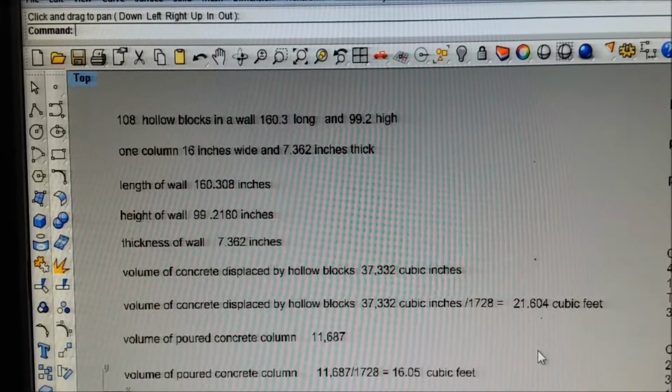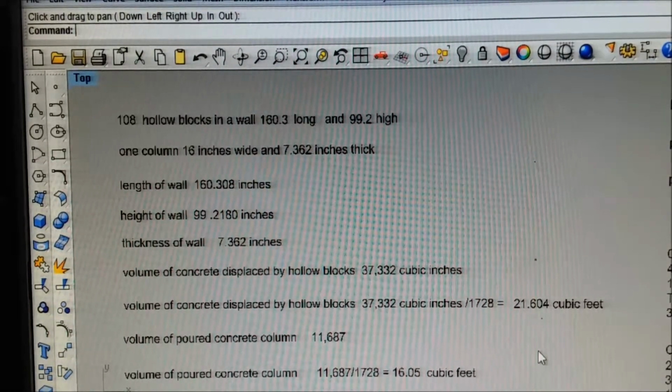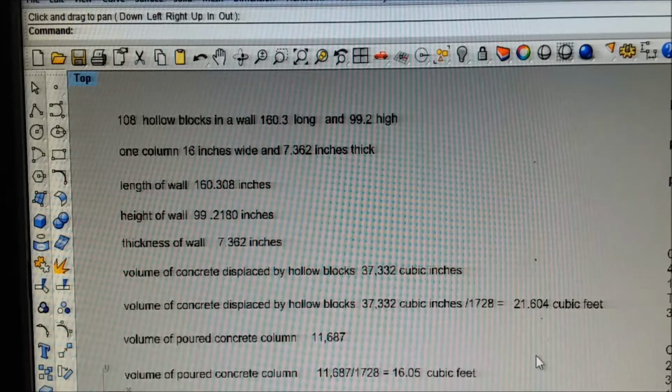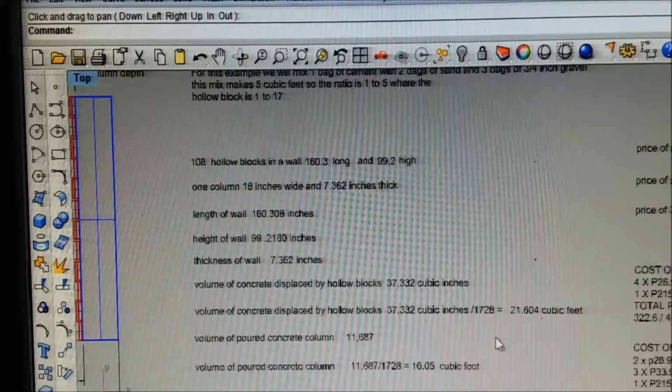It's poured concrete, but we mimicked the standard hollow block construction. If you had both of them sitting in render, they would look exactly the same. But particularly our top beam has got the same stirrups and long rods as if it was a standalone beam. So it could carry the building if the poured concrete wall was not underneath of it. I don't know how strong that thing is, but it's plenty strong.